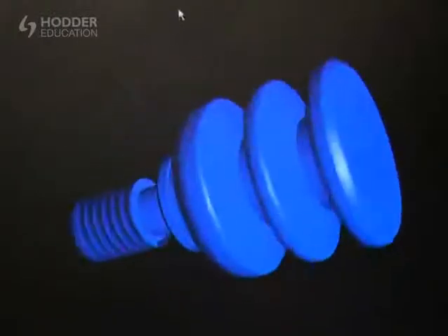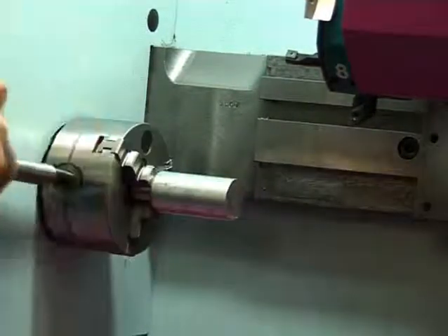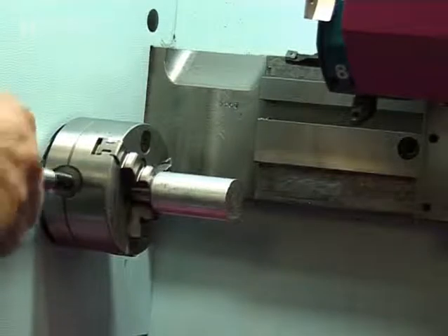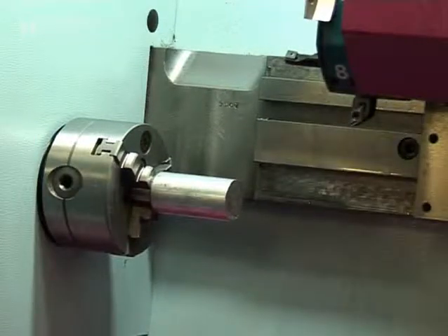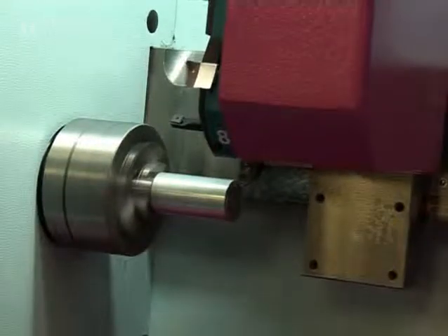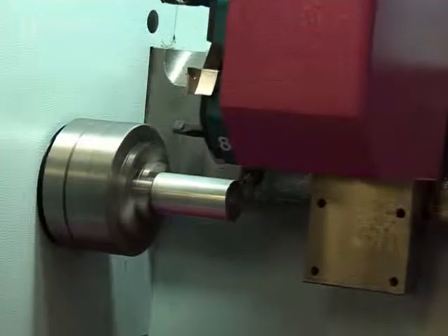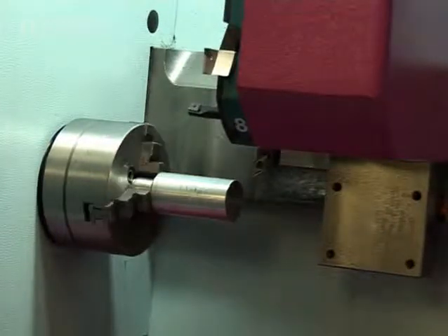The turning machine works by putting a piece of raw material, we call it stock or bar, in the machine, and it uses a variety of different cutting tools to machine the profile we want. There'll be tools for doing drilling and internal work. There'll be also tools for forming the external profile. There'll be a special tool for cutting the thread.